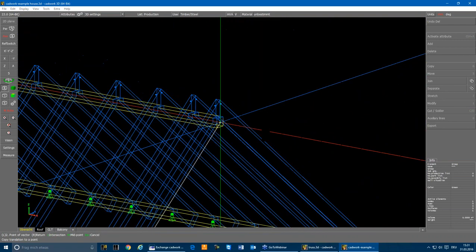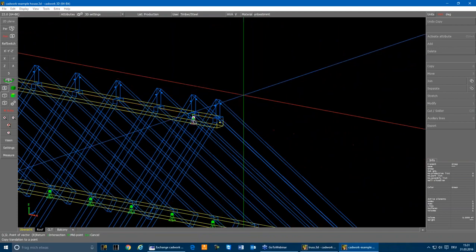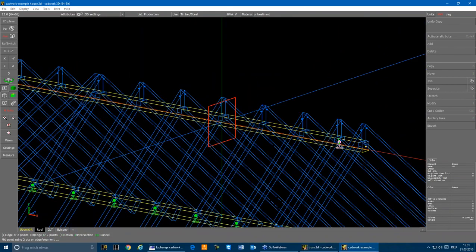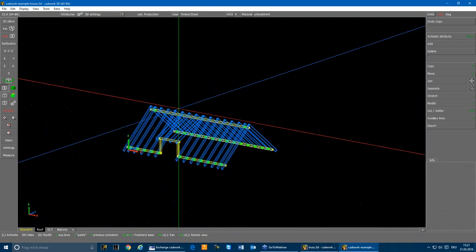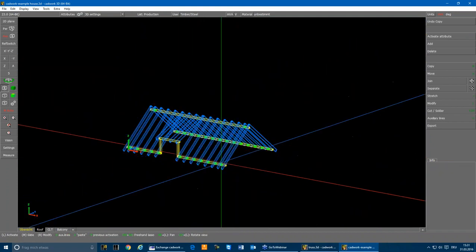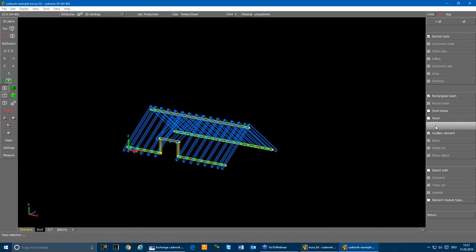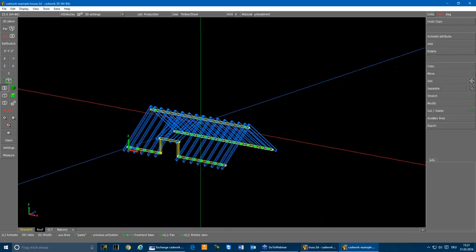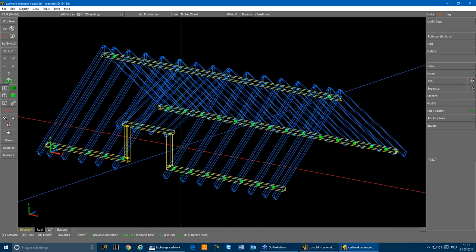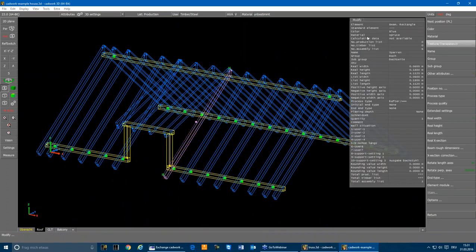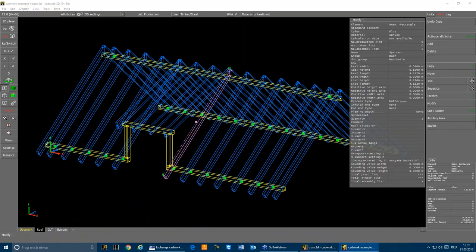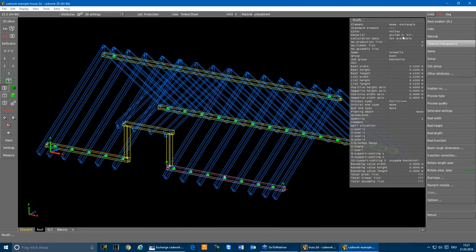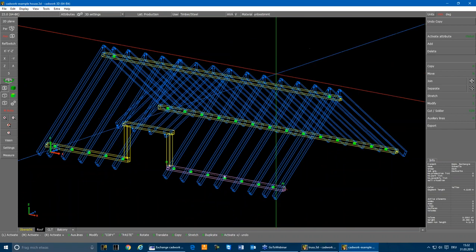So it means now we will put it from here to here to have a support in the ridge beam as well. Copy it to the other side to the midpoint of this ridge beam, and we do this with all the supports we need. By switching off the auxiliary elements, now we have a model which looks like this. So this is now including the rafter with, for example, material spruce, and the purlins and posts with the material glulam as well, like we had before.